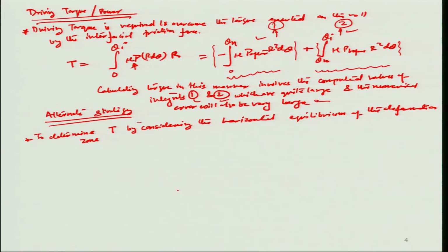and this is shown right here. So you have now many forces which come into play. This is, let us say, the whole volume of the strip, where on one side the thickness changes to some T final value, and on the other side it starts getting pressed into the roll at thickness T initial, and you are having torques on both sides.